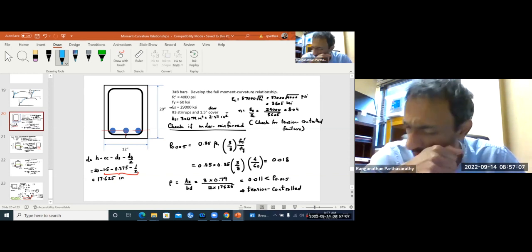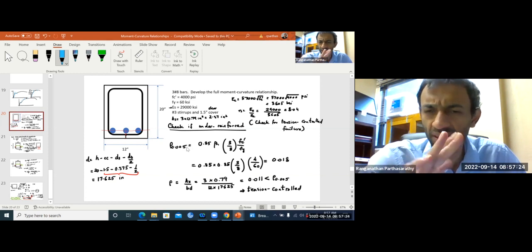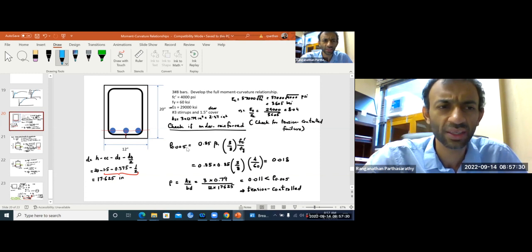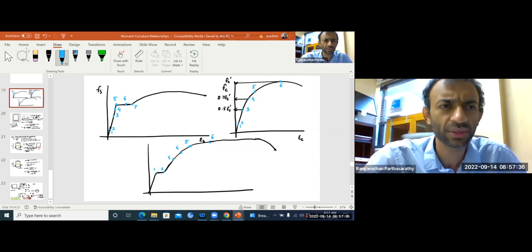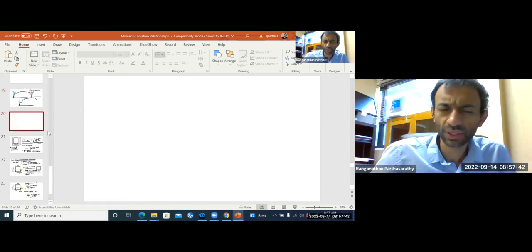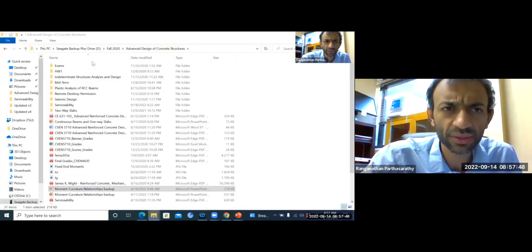Okay, so this is our example, an under-reinforced beam. Do you all remember how to check whether this rho, epsilon 0.005, how to check whether the beam is tension controlled, how to check whether your reinforcement is within the tension control limit? Maybe let's do a recap. Let me take a new page for that. Let me actually use the slide from the undergrad course.